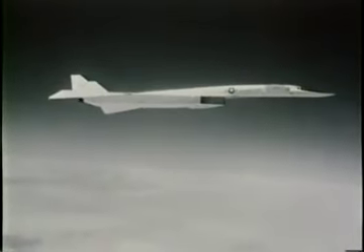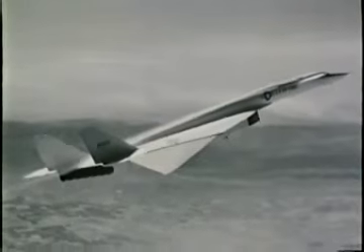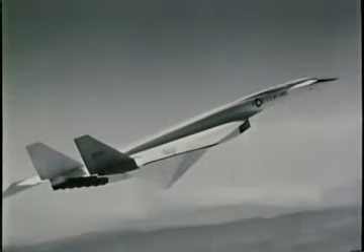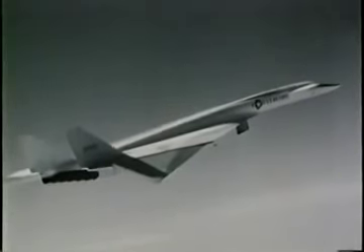In summary, we have seen 3 important phenomena which occur in adiabatic channel flow. Choking implies sonic flow at a throat with an upstream flow which is independent of downstream conditions. Blocking implies choking at 2 throats in succession, with the second throat area too small. Starting implies swallowing of a shock wave and is a necessary step in the achievement of supersonic compression or diffusion in channel flow of a compressible fluid.